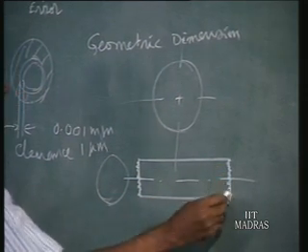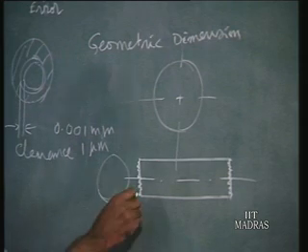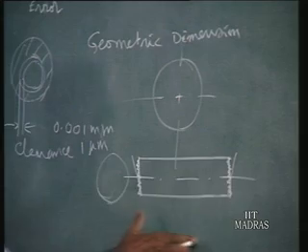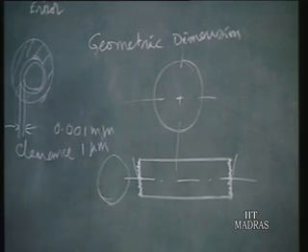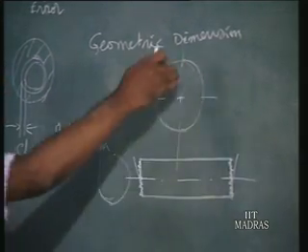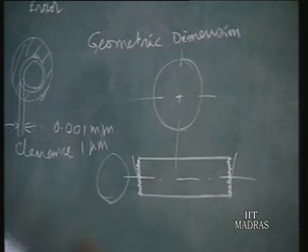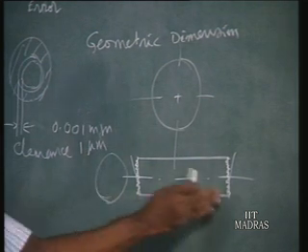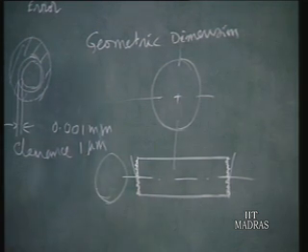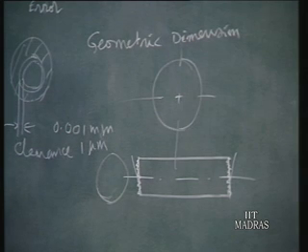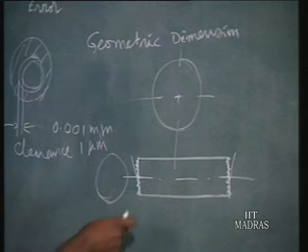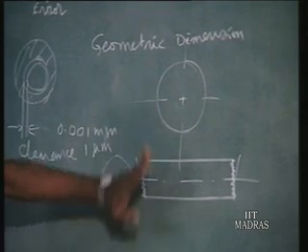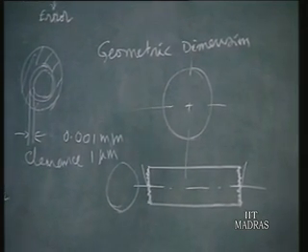So when we measure the length of the rod, if the surfaces are slanting, we will have one dimension at the bottom and another dimension at the top. And if it is not plane, if it has shallow ups and downs in the macro dimension, then it depends where we put our measuring instrument. So even though we simply say length, the actual length is difficult to decide. These are abstract dimensions which may not be realized in practice.